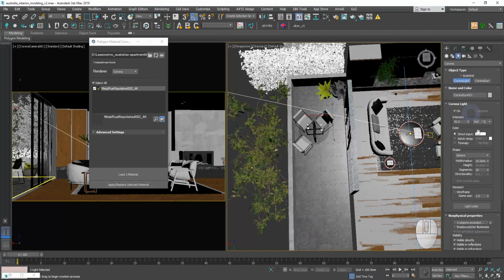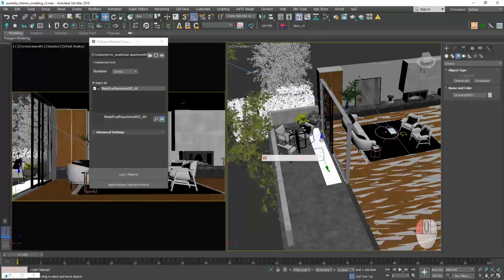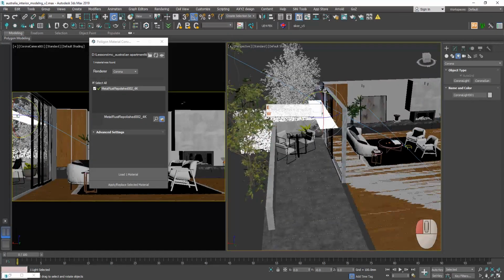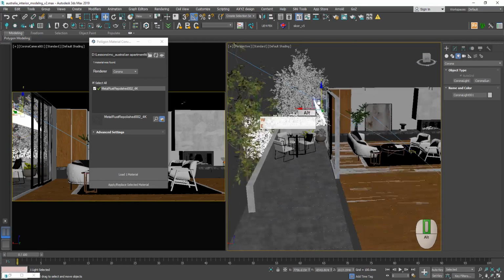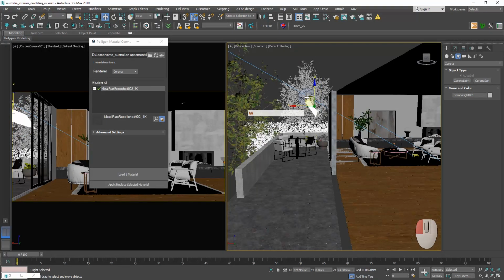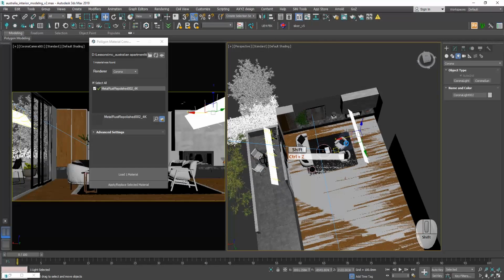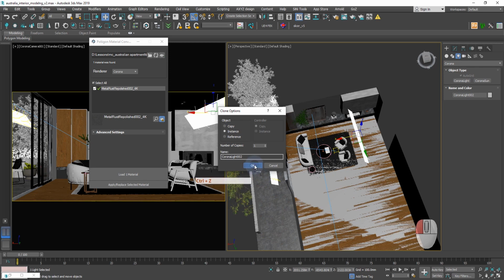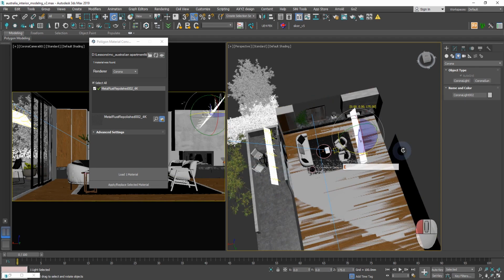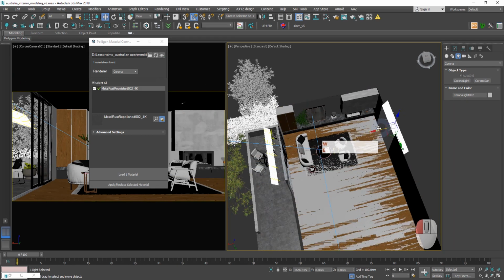We will use a rectangle with auto grid here. We create it with ratio like this. Raise this Corona Light and point it at the ceiling. Copy it with Shift held down, instance OK. Turn it 180 degrees and put it on the other side.